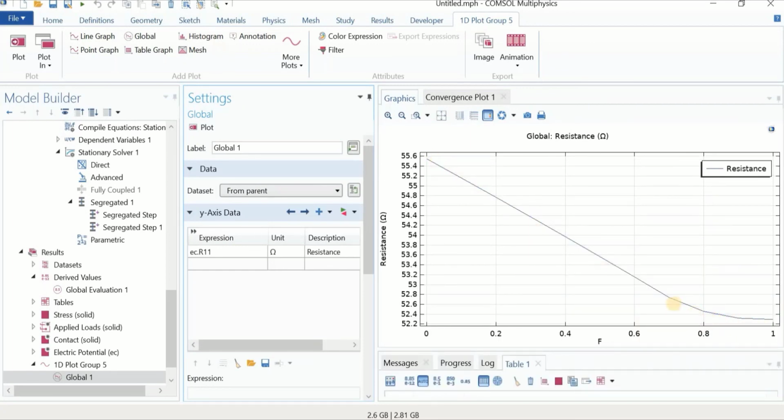So you see we have the resistance decrease as the force is applied because you have more contact area and more electrical junction from the electrical point of view, right? Okay, this is very interesting. In fact, you could monitor the effect of the change of force and the resistance. And it is not a very practical case. We just want to show you how to model a microstructure and a force sensor based on the resistance change of the overall system. I hope you enjoyed this video, so stay tuned for the next videos.